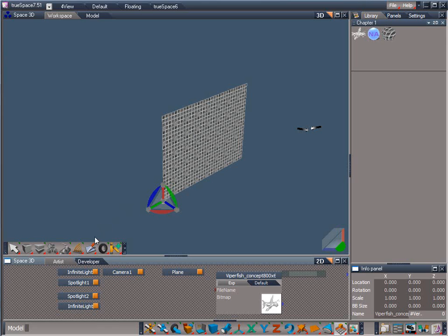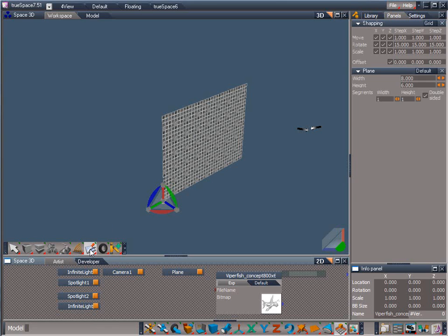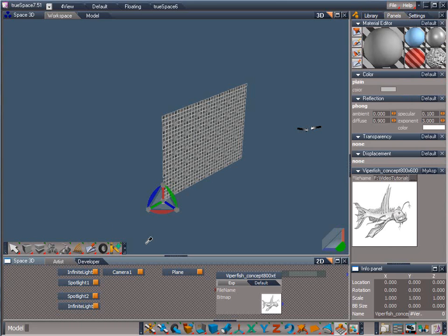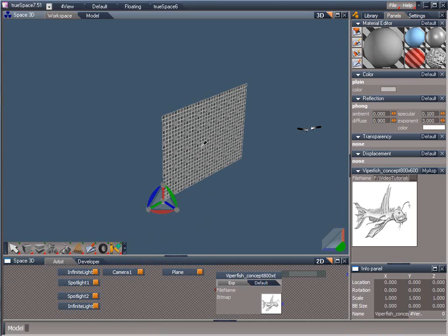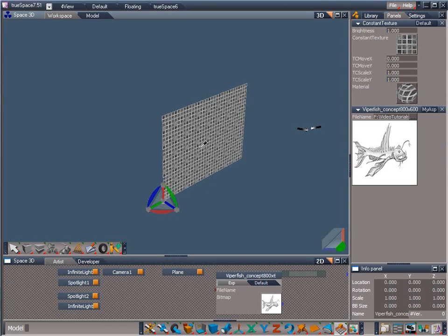Find the Material Inspect tool in the toolbar and click on it. This initially brings up the V-Ray material editor in the stack, which is something that we will go over in more depth in a later chapter. With the Inspect icon still active, click on the plane. Since this is a DirectX 9 material, the Inspect tool will bring up the Materials panel in the Panels tab of the Stack view. If this had been a V-Ray material, it would have instead filled in the V-Ray material editor with sampled values from the material.